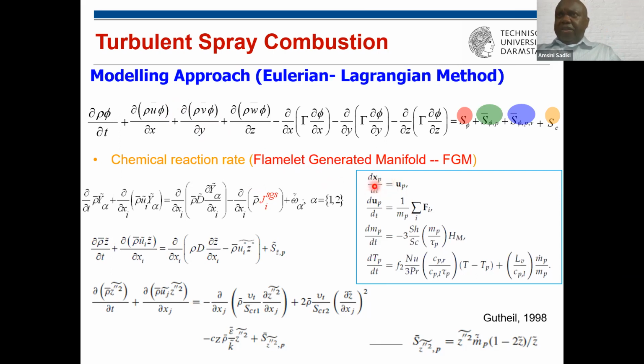So we have now the transport equations, and what we have to solve for the motion of our droplets with appropriate forces. We have this equation for the variation of mass of the particle, and I summarize everything here as we have seen yesterday. This equation we also introduced yesterday, for the Lagrangian part and for the Eulerian part.